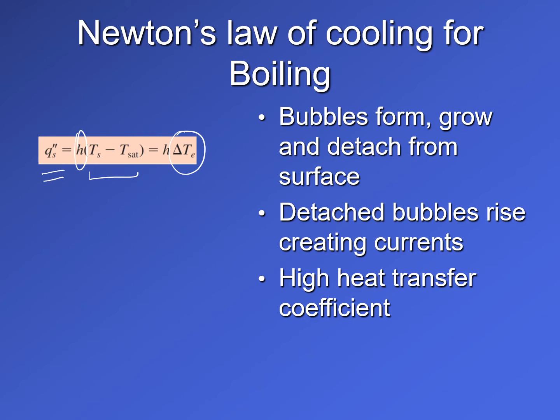The bubbles grow, and as they become larger because of the buoyancy force, they rise up in the liquid as they're lighter. In the process of rising up they detach from the surface, and these bubbles then apply a force on the liquid which is equal and opposite to the drag force the liquid applies on the bubbles. So this creates currents in the liquid in which the bubbles are rising.